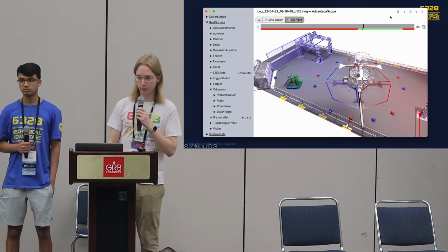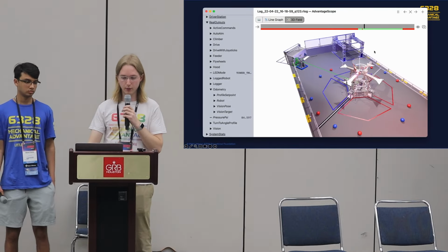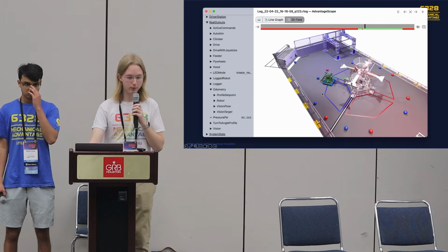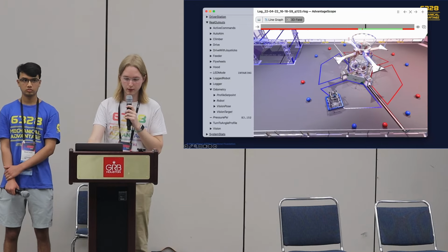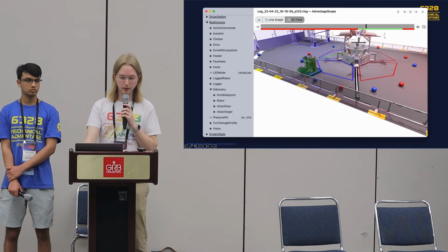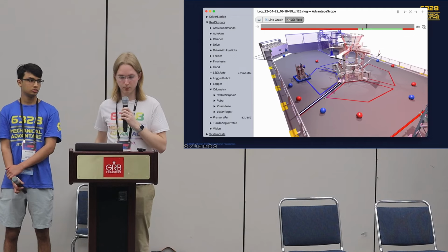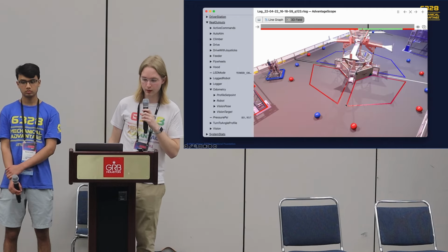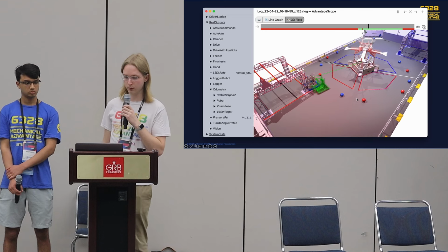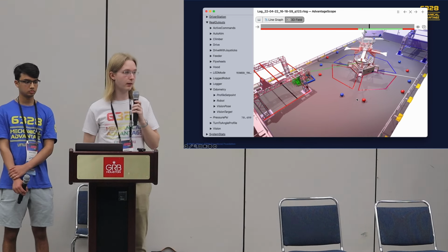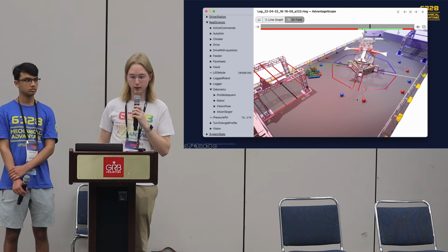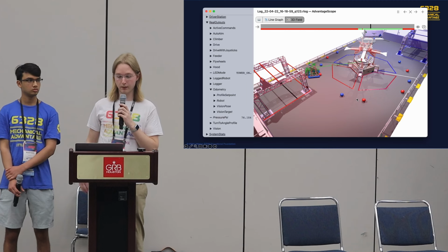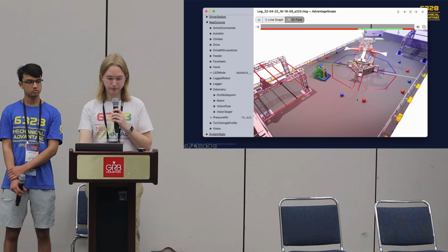So here, going back a couple of years, this is our 2022 robot using vision data and a Limelight to reset its odometry. So the green line shows when that reset is happening, and the green robot shows where it's resetting to. Now there's a fairly complex pipeline involved here, especially because we were using retroreflective tape, and filtering out invalid targets like reflections is critical. Now this match is an example of the pipeline working well.